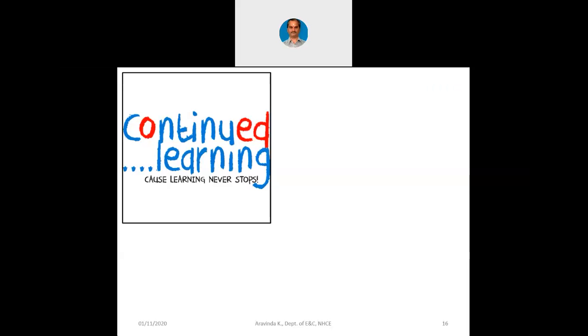And when you studied emitter follower in the first module, you would not have thought that it is having a feedback also there. But emitter follower also is going to have a feedback, because when the emitter resistor is having the output voltage across it, that itself is causing the reverse biasing of the base emitter junction. That way, in many circuits, even when the feedback circuit or the feedback concept itself is not present, there will be an indirect feedback happening in those circuits. That is why we had seen some examples,